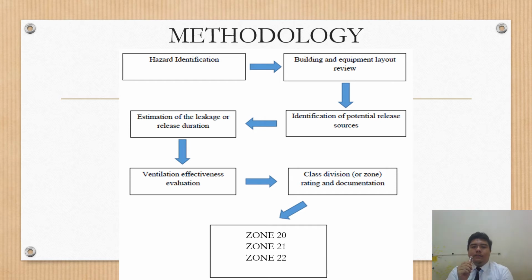This is my methodology for my research project. First of all, I need to know the hazard identification. Hazard identification is required to identify what substances are in the environment to be classified and their features. For this purpose, it can be identified whether the material is combustible for the purpose of assessment of ignition source, and determine the material characteristics such as particle size, moisture content, cloud and layer minimum ignition temperature, electrical resistivity and appropriate dust group.